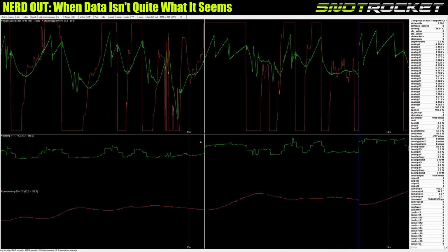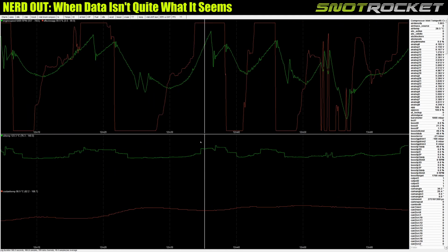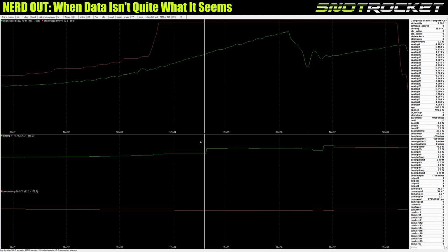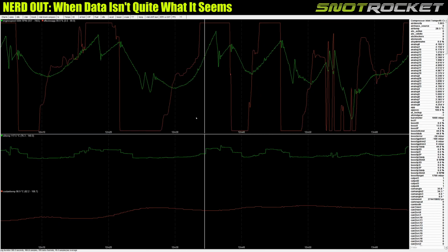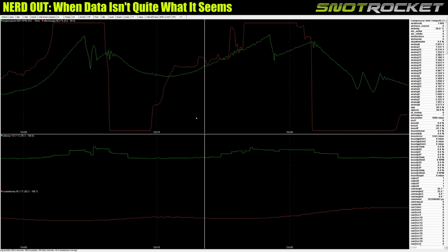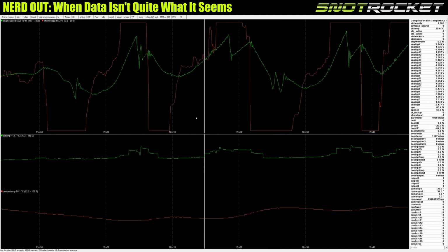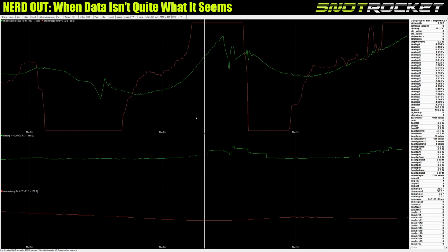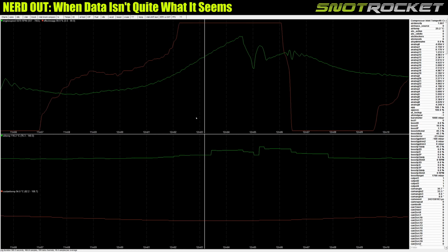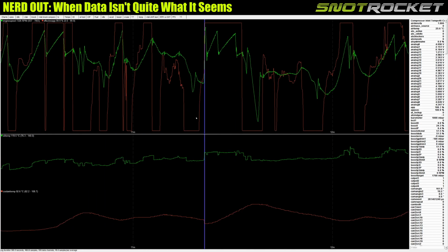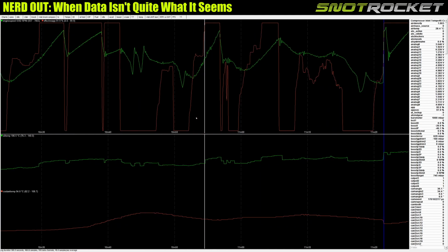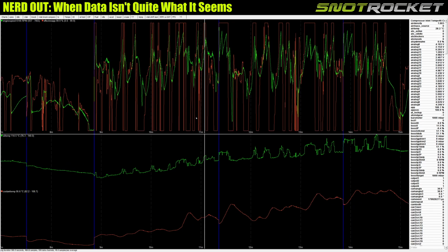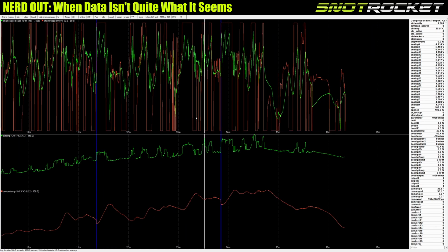I thought, right, okay, so maybe it's speed related. So I went to the next one. We look at the start of the spike, and it's roughly at the same speed again. If we go to the next spike and look at the beginning, roughly at 5,500 RPM, and so on. So looking at the start of each of these, it's roughly 5,500 RPM where this spike happens across the board. 5,500 RPM there. The next one, 5,500 RPM. So I thought, right, well, what's happening at 5,500 RPM that could be causing this?